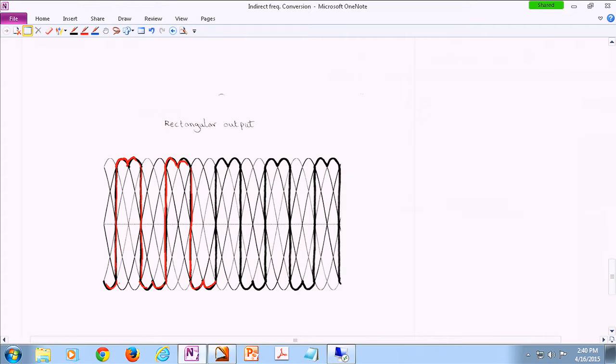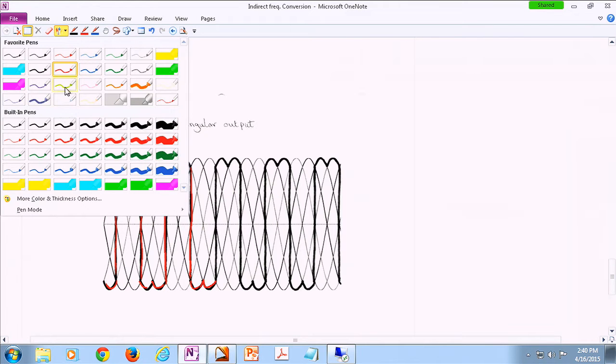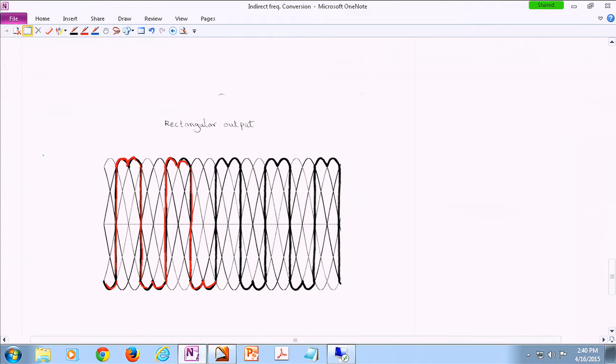So did you really need an AC signal that is a square shape, or did you need an AC signal which ideally had to be sinusoidal? So you can argue that looking at the fundamental harmonic frequency of this, it is something like this, and actually the frequency of the signal is higher than the line frequency. So again, you can even achieve higher AC signals as well.